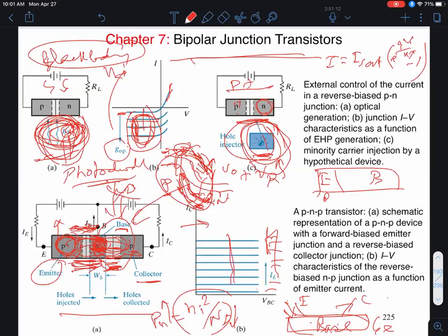You make two PN junctions in close proximity. So the question was, why do I need to make this base between the emitter junction and the collector junction narrow, and what does that mean? Well, the reason can be understood by looking at the carrier distribution in this forward bias emitter base junction. So in the P plus emitter, the current is very low. In the base, I get a higher hole current that is dying down exponentially with distance. Remember that? It's e to the power minus x over LP.